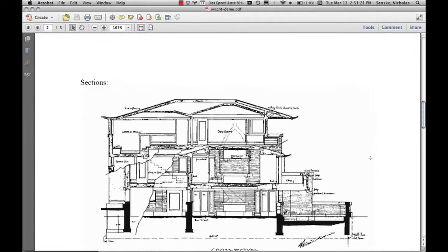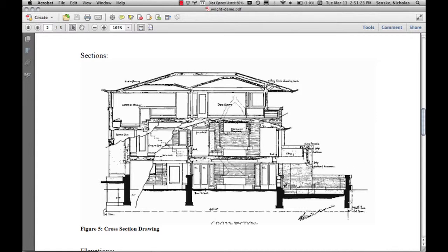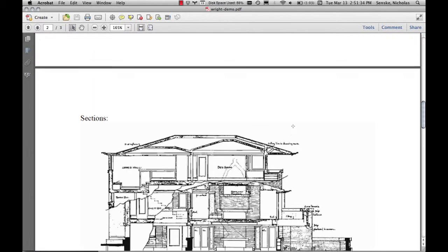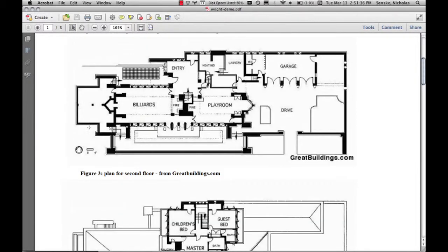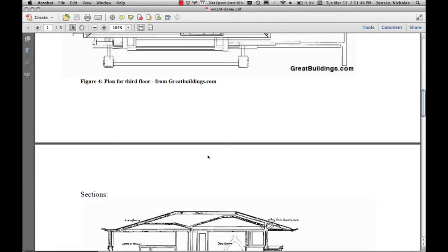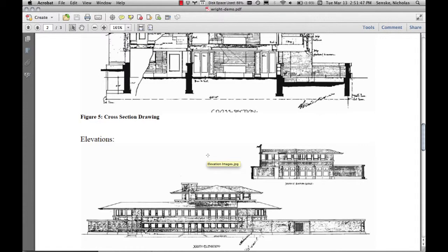Okay. And then we also have some other drawings, and we can make these work too. Like this actually has a, well, it's kind of a center line, but this says 60 foot, if you can see that. We could use this as a scale because we know that there's this edge of the building and this edge of the wall. And so if we didn't have this scale, we could take this measurement and we know that that's 60 foot. Right. Okay. So the first step is just to make everything coordinate, like scale everything so that they match up.